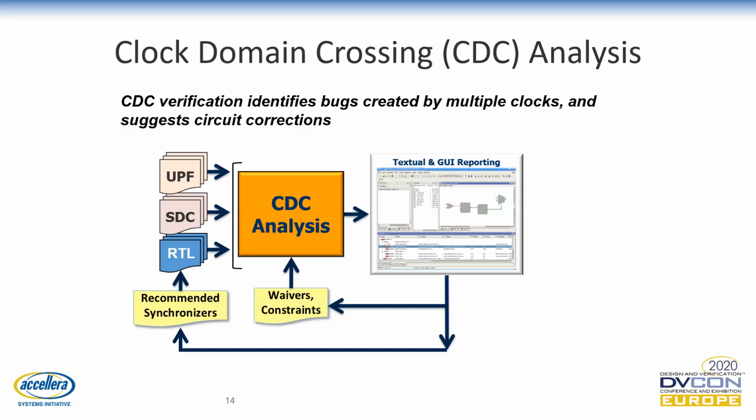So constraints are required to specify asynchronous clock groups in the design, as well as the clock domains of the input and output ports. At this point, manual design reviews will encompass both the design and the design constraints. Unlike with previous analysis, corrective actions from manual reviews may be to modify the design constraints rather than the design RTL itself.